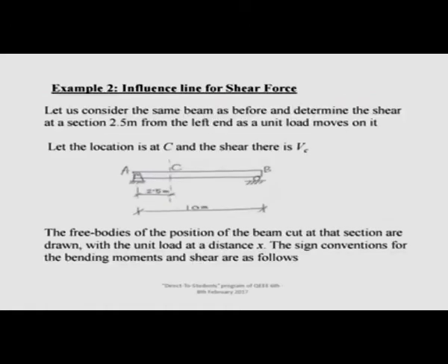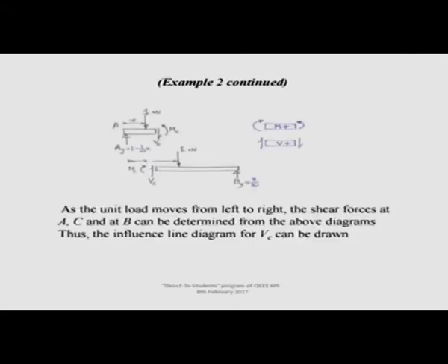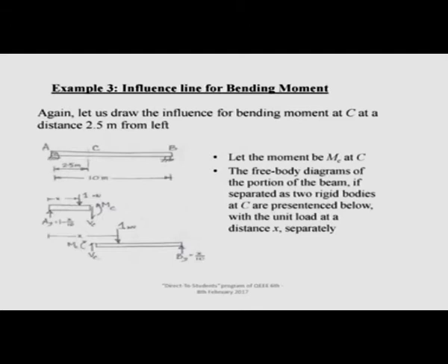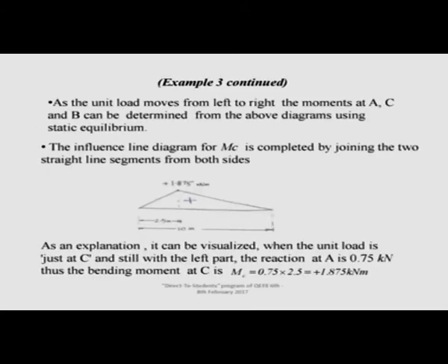And next is the influence line for shear force, how it looks, and also a special emphasis on clearing your sign convention. I will suggest you draw the shear force diagram for the load here, draw it and understand the sign conventions as well as the difference between diagrams. Next, we have drawn the influence line diagram for bending moment at a particular section. So, and then this is the diagram.